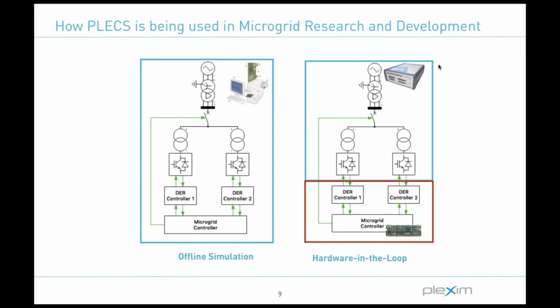On top of that, you may have microgrid to DER control interactions that are all happening in real time on actual control hardware, but looking at this virtual plant. This way, different processor-specific quirks, implementation issues, as well as the control and communication systems between local DERs and the microgrid controller can all be tested in real time.